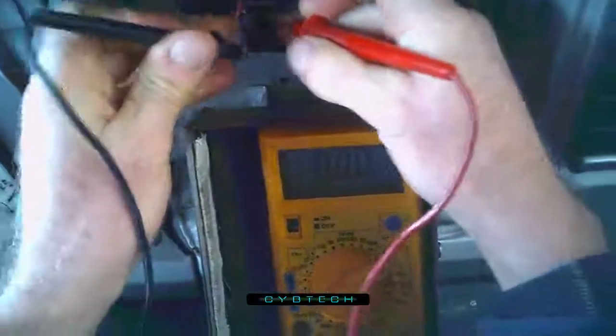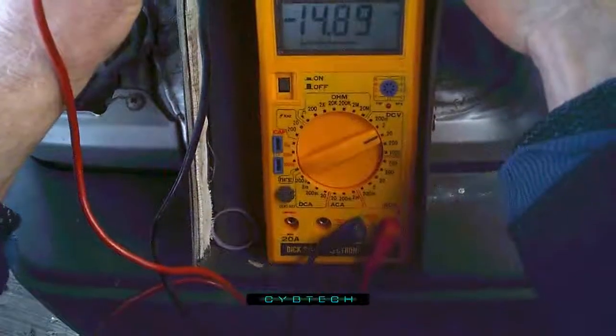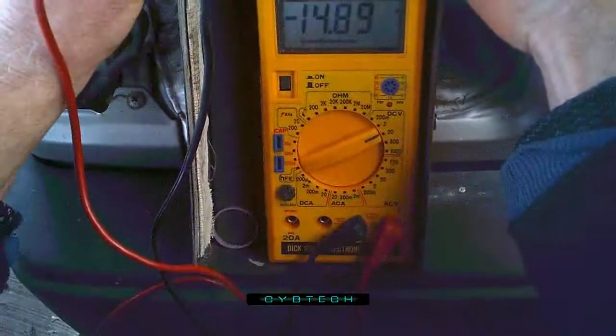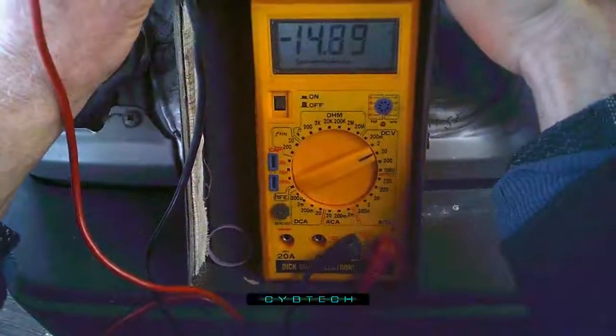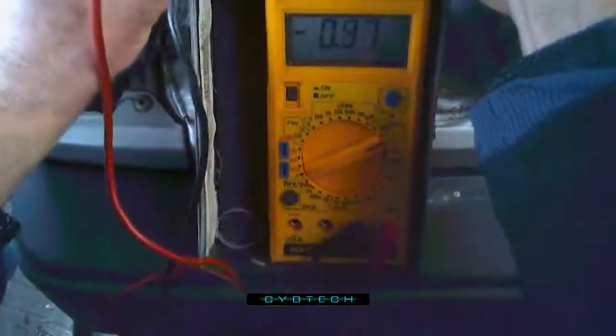I tested the socket. There was power at the light socket okay, but I noticed something strange. The voltage seemed backwards. I tested between the chassis of the vehicle and the socket. It then became apparent that there was positive voltage on only one terminal of the socket, and it wasn't switching between high and low beam. It was just on all the time.